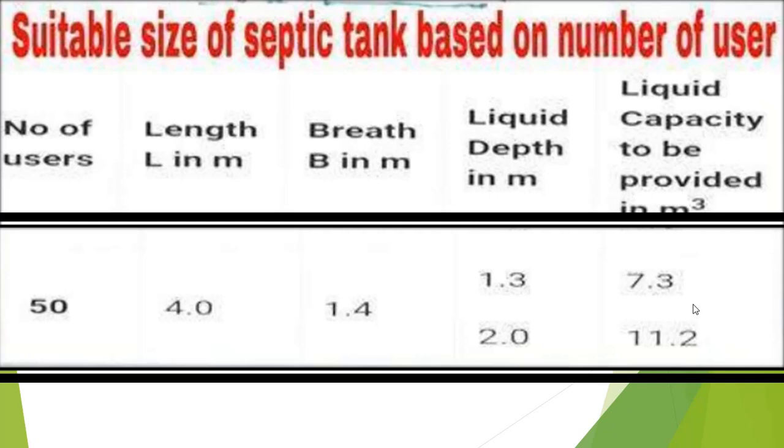The detention period of the septic tank should be considered to be 24 hours mostly. For the inlet pipe, an elbow or tee of 100 mm diameter should be deep below the liquid at a depth of 250 mm to 600 mm, and for the outlet pipe a depth of 200 mm to 500 mm should be provided. The inlet baffle wall should be at 1/5 the distance of the length of the wall. The baffle wall should generally extend 150 mm above, and 400 mm to 700 mm below, the scum level.